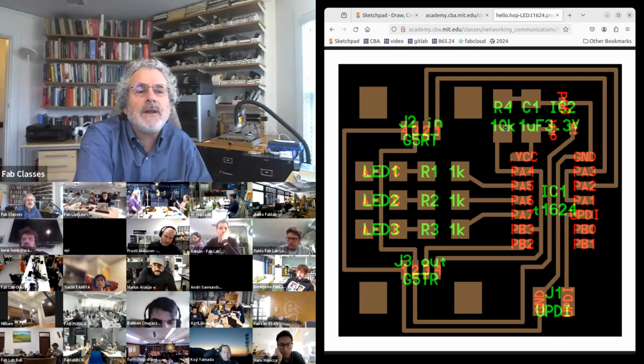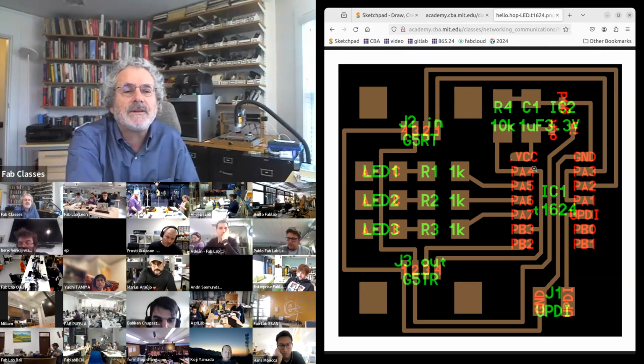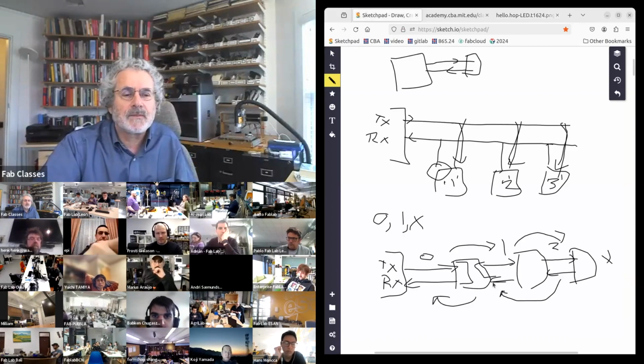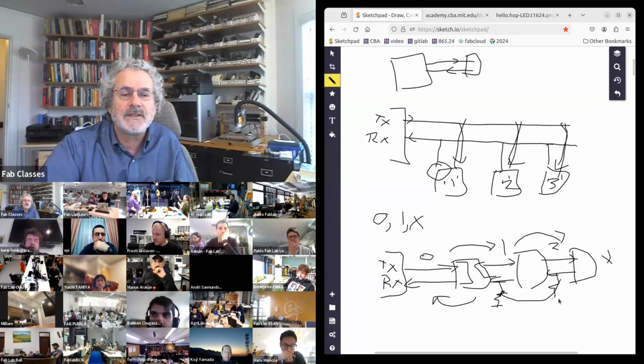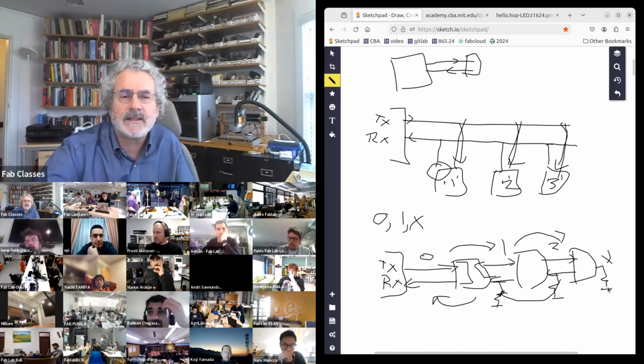I should mention there's one other resistor. On the output port, on the receiver, I've got a resistor pulling it down to ground, this one here. Each of these on the board has a resistor that pulls it down, and that's how you can tell if anybody's connected. When somebody's connected, the line is high. If nobody's connected, the line is low.